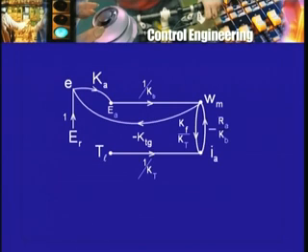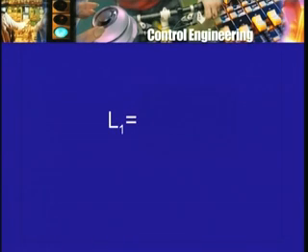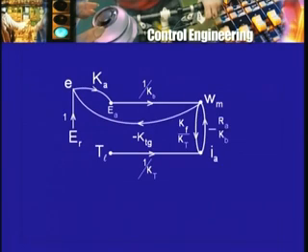So that's the loop, and for which the gain will be given by minus Ka Ktg divided by Kb. There is the other loop from omega m to Ia, and why does that path occur? Because it is multiplied by the coefficient of friction. So this is the torque required to overcome friction divided by Kt, and therefore this is a part of the armature current that is required to overcome friction.